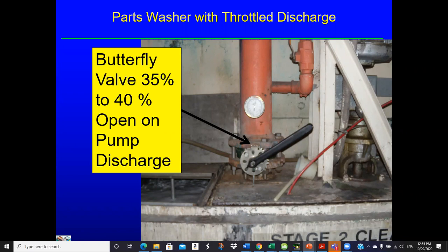The first one is hot water rinse. And the second one is detergent. And the third one is this, and the fourth one's this, and the fifth one's this, and the sixth one, the seventh one. By the time you get through, that stuff's been washed and rinsed and all that. And then they hang it, and it dries on the conveyor as it's heading in. And then they paint it. You got a guy spraying it or a robot spraying it or whatever. And then they bake it in the ovens.